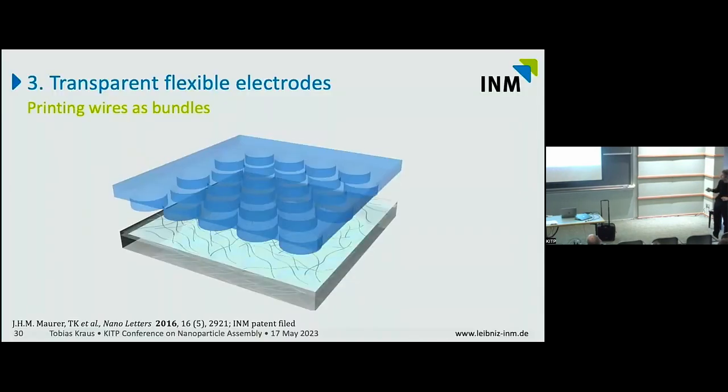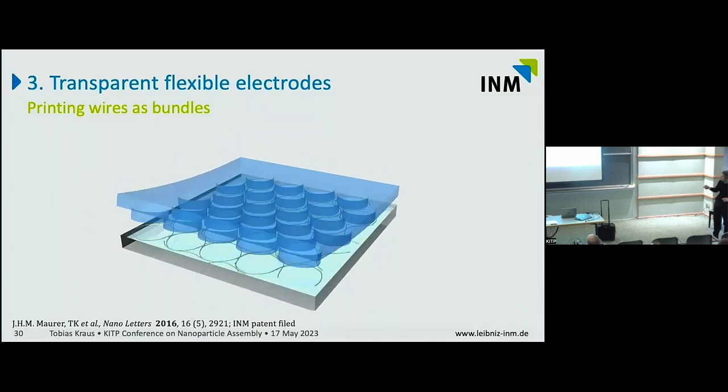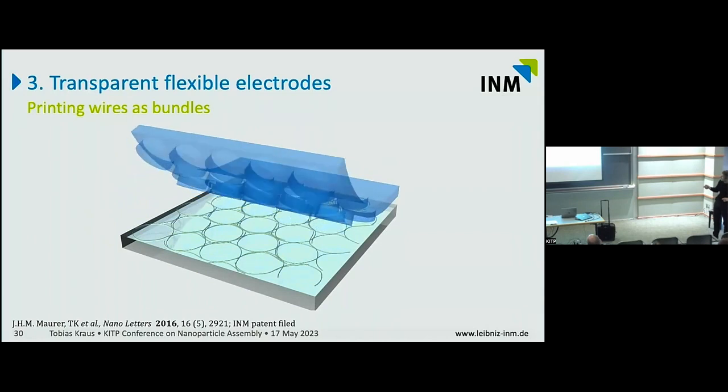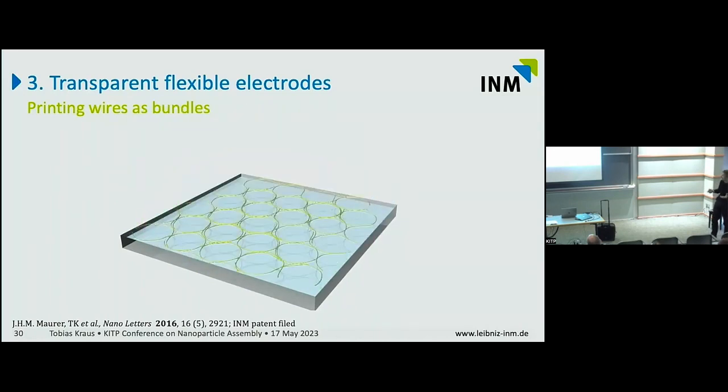And this is what's happening. Here's the polymer stamp, in this case with this kind of hexagonal or triangular packing. The wire mesh forms. Plasma treatment removes the organics, which is very critical because it wouldn't be conductive without that, even though we would love them to be such that they already are conductive before. And then you've created this kind of mesh.